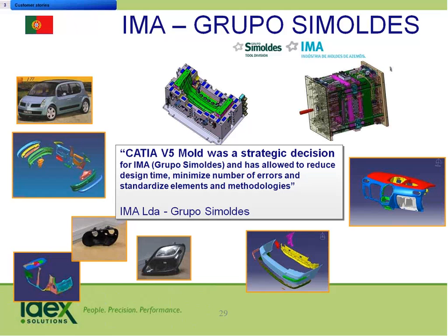So what I need to do is take that upper control arm and design it in a way so that when I put it on the car, it loads and goes into the right position. And not only do I want it to go in the right position, I want to make sure I have clearances, I don't have clash, and nothing behaves wrong. Typically, that's been a real challenge in the past, to design the part and guess how it's going to deform. So that's what Realistic Shape Optimizer does. You take the FEA analysis, it'll take the part, show you how it's going to deform under load conditions, and show you what it's going to look like.